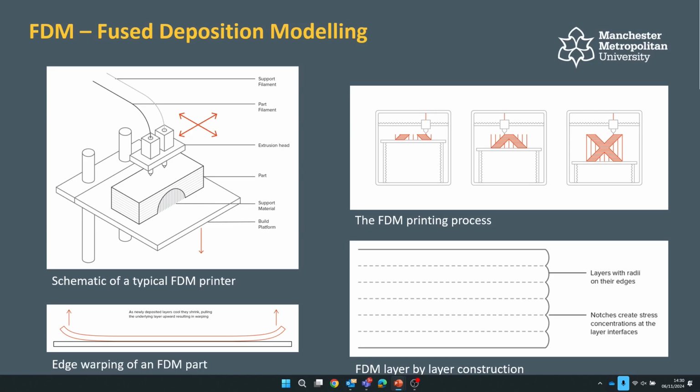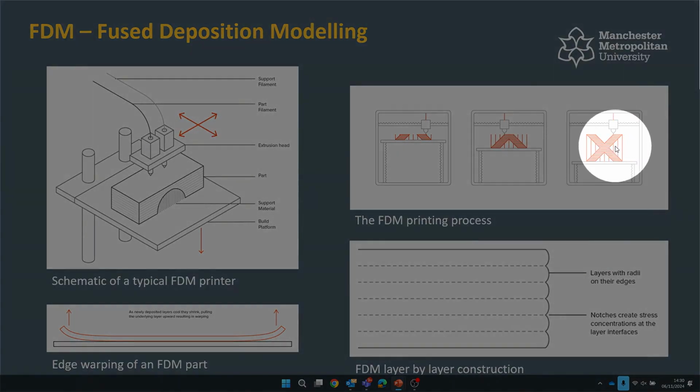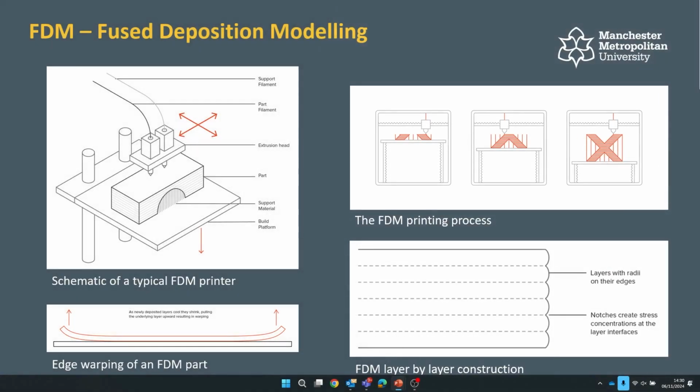Any overhanging objects, like we see over here on the right, it will build these little vertical supports, these little scaffolds that you would then break off afterwards. So it's a really, really nice way of making models, I would say. And nowadays the materials have come along so far that you can get all sorts of different types of materials, from PLA plastic, ABS plastic, to weird filaments like flexible materials, wood materials, magnetic materials, all sorts of stuff. You can do some seriously cool stuff with 3D printing.